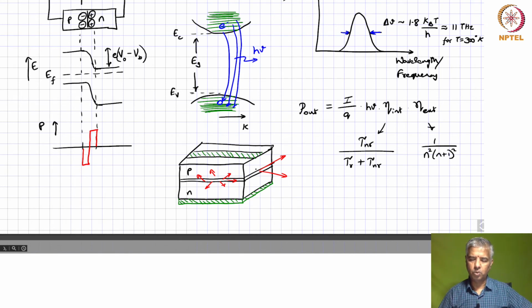So now, how do we look at a laser diode? Well, the laser diode could be a very similar structure, the double heterostructure and all that, with the same PN material and the active region and so on. The only big difference is that for the laser diode you also have a mirror in these regions.